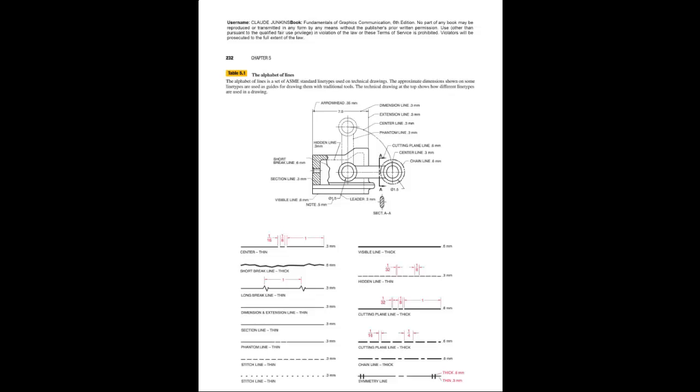custom line styles. Custom line styles are designed for use on underground utilities. I'll show you an example in our labs of our campus maps, which show where all the underground utilities are. So something like a gas line would show up as a long line with a dash and then a G in it and a dash and another long line, so that repeats itself throughout. So when we look at our map, we can tell exactly where all of our utilities are underground and what those utilities are by just the designation on the line style.